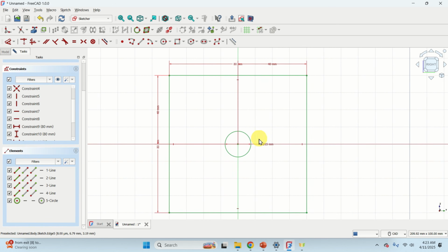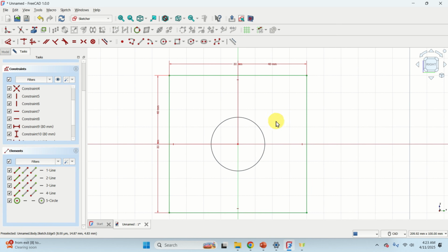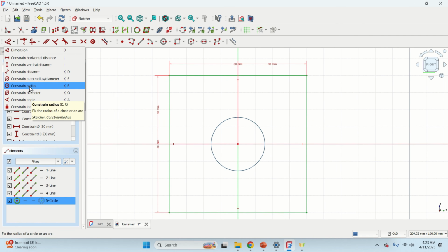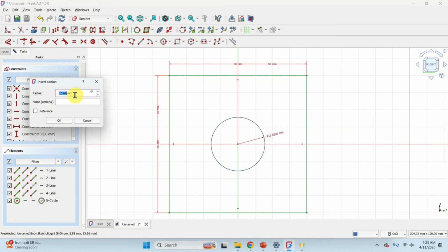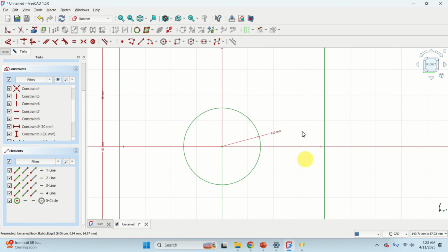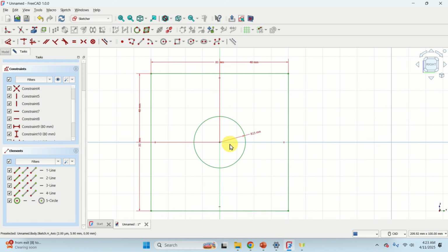Okay, another way to create a circle, let me show you after I erase this, is to click here, click on the center, specify any radius, right click to exit from this menu, then over here select the circle, and then click over here and here to constrain the radius, and let's go with 15 for the radius. Okay, so make sure that the radius is 15. That is, in the previous case, the radius should be 15. Good. Let's continue.